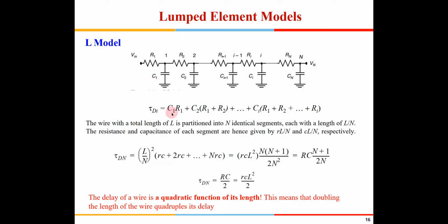Yeah. Okay. So this is the equation. Now each of them, if I replace C, I replace it with L, the total length. N is the number of segments out here. So L divided by N. C is the capacitance per unit length, so I have replaced it with C divided by N here. Similarly, R has been replaced by L by N into small r.